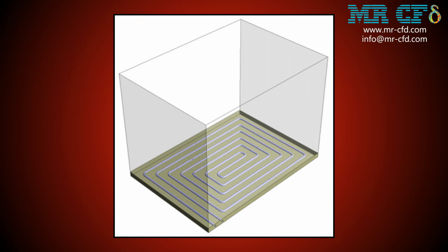The present model is designed in 3 dimensions using Design-Modeler software. The calculation area of the present model is related to a room with a length of 3.6 meters, a width of 2.6 meters, and a height of 2.6 meters, and a layer of concrete with a thickness of 0.12 meter is designed as a solid area in the lower part of this room. Inside this concrete layer, a 0.04 meter diameter spiral pipe is designed to be inserted circumferentially, and after a spiral path across the floor of the room is led out of the room.